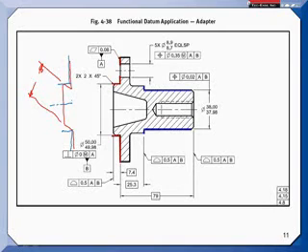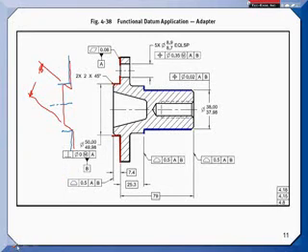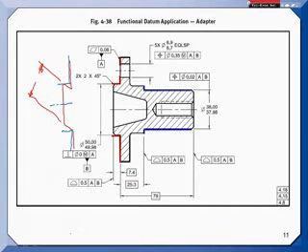The standard doesn't say datum features are mutually perpendicular. In fact, there are many times they aren't. The datums themselves are. The whole theory behind datum reference frames is, if you go back to the 1966 standard, and I really like to have my datums in red, so I'm going to do that.